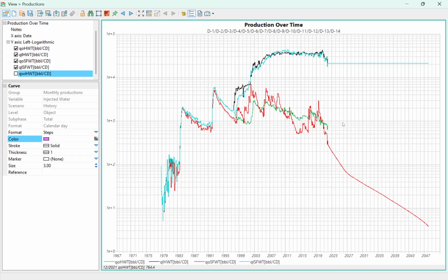But when you have a good fit with liquid, that means that your flow elements and your coefficient distributions are fine, that they are probably correct, but your oil is not as well fitted as the liquid. You may need to review the calculation method that you're using. Maybe instead of using segregated flow, you may need to use, for example, the characteristic curve, the statistical curve, or the WOR method, or any other statistical method.